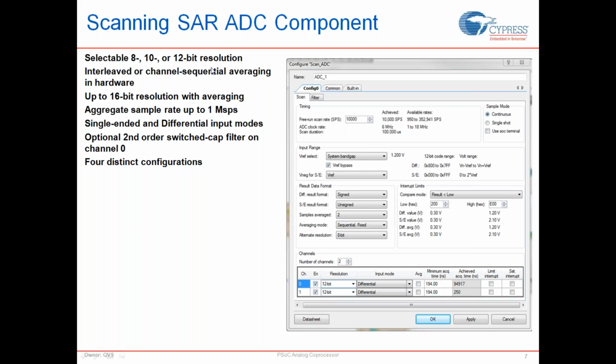The reason for this is the SAR ADC is really a switched capacitor-based model of an ADC. So it's going to switch your input into a capacitor. It's going to compare that against a reference by switching the reference into another reference capacitor. So since it's a switched capacitor that is connecting to the reference, you're going to see some amount of input impedance on that reference.